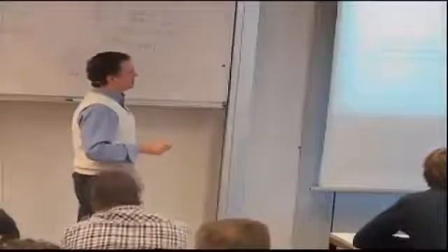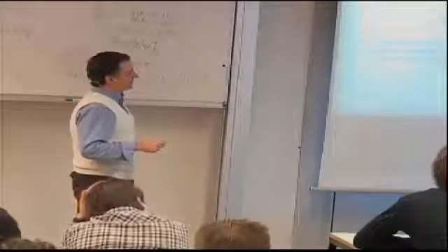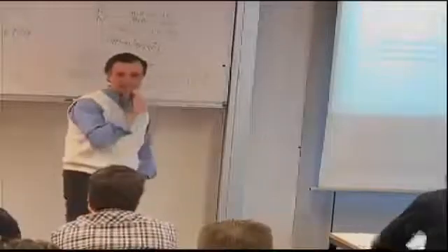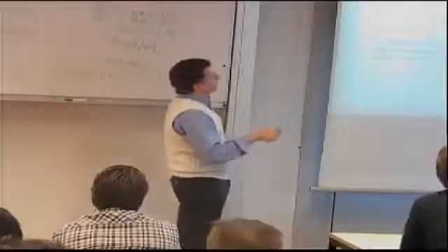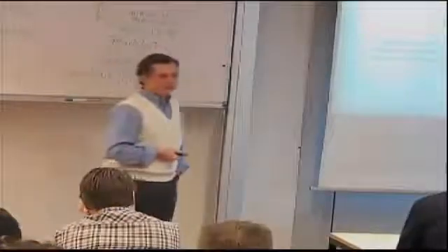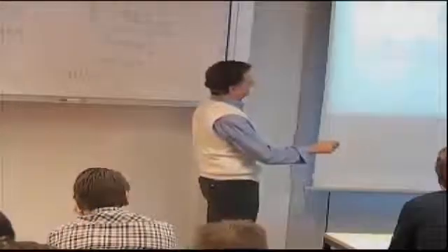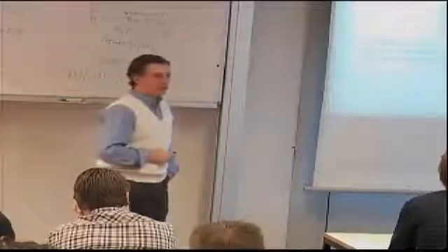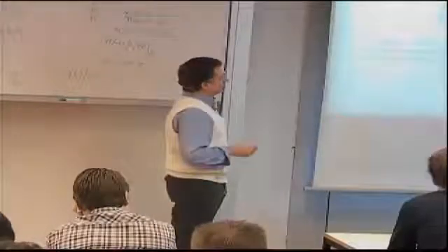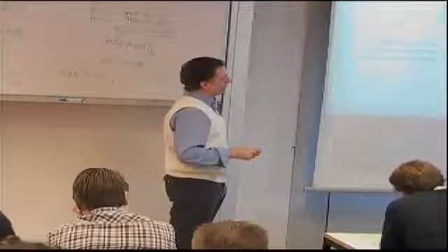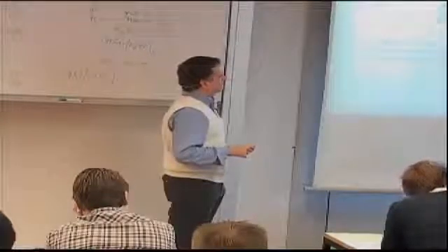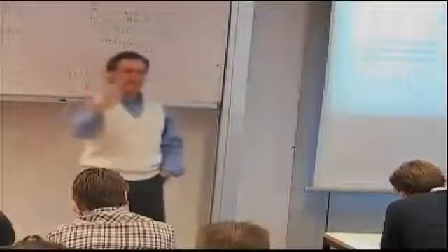Now there's one more problem, where we say, okay, we actually tested this laminate now, but we did not test it at room temperature. We tested it at the elevated temperature wet conditions. And we found that it failed at half the load that you predicted in part 1, because part 1, for one thing, includes only room temperature values, doesn't account for the fact that it's conditioned with moisture, fully saturated with moisture. So if there were no damage in the specimen, but someone told us this is an A basis specimen,